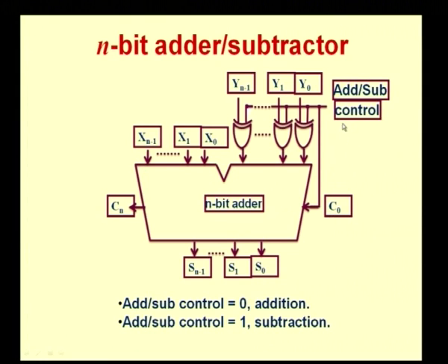Okay. So, let us see how this will do both addition and subtraction with the help of this control circuit. Once I have this control here with a value of 0 given as the input, now, when I give 0 as one of the inputs to an exclusive OR gate, the output of the exclusive OR gate will just depend on the other input. So, if I have a 0 here, the output will be 0. If it is a 1 here, it will be a 1 here. That is, if one input is 0, it will just pass the other input to the output, which is what I want, right, because I want to do an addition, I want my x's and my y's as direct input to the n bit adder, and I also want my C naught value to be 0. Since for an addition operation this control signal will be set to 0, this control is what is coming as input over here. So, C naught will be equal to 0, right, and this whole thing now will act as an n bit adder.